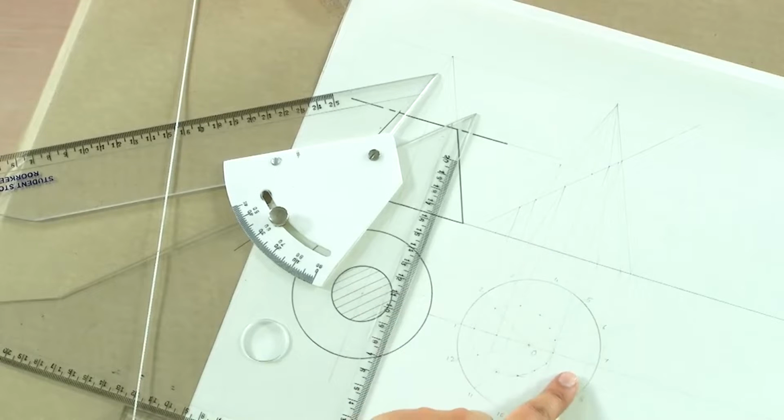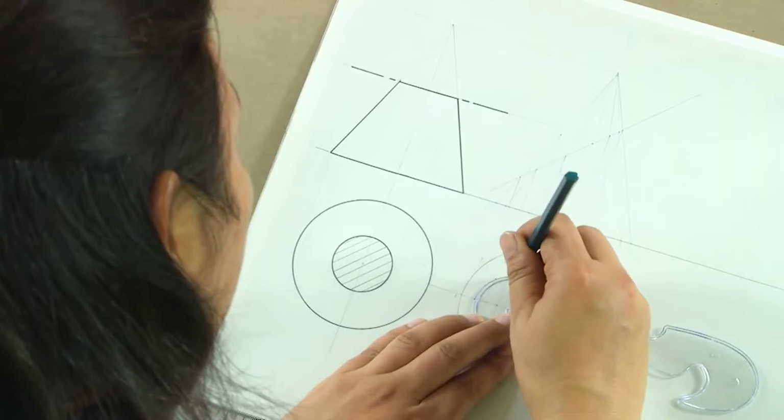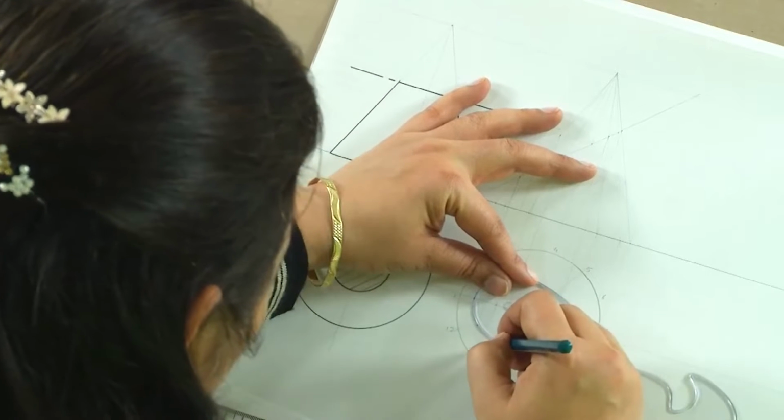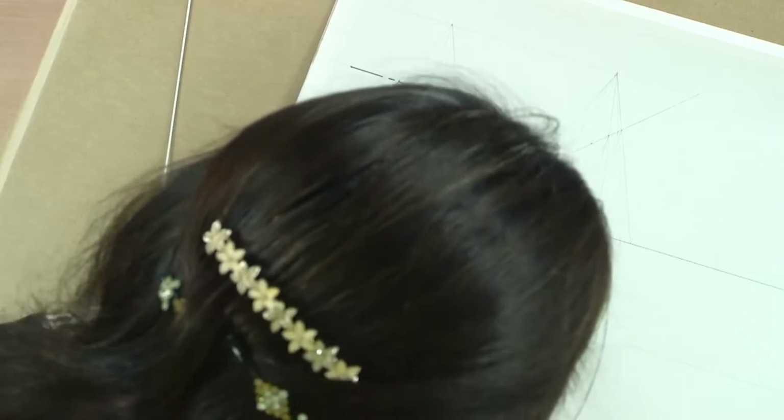We still have the rest of the cone intact, but these generators are all imaginary. So we won't have them here. We will not be seeing them in the final drawing. The final drawing will actually be having only this. So that's what we will darken. What I have done here is, I have just tried to join these points together to give it the shape which this ellipse has. So this is the shape of the ellipse that we are getting.